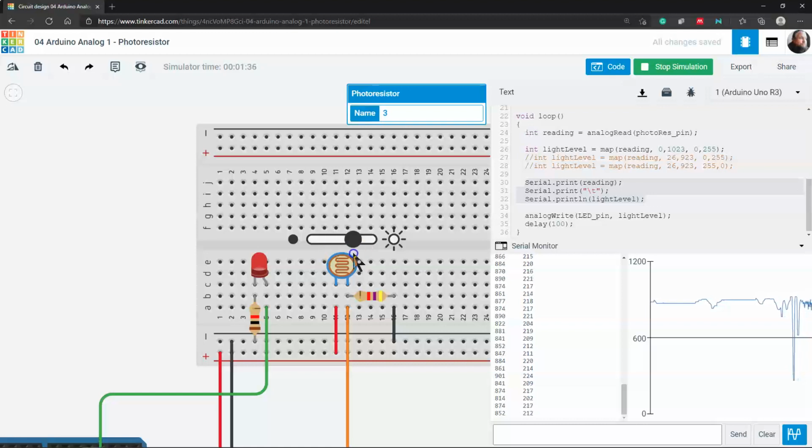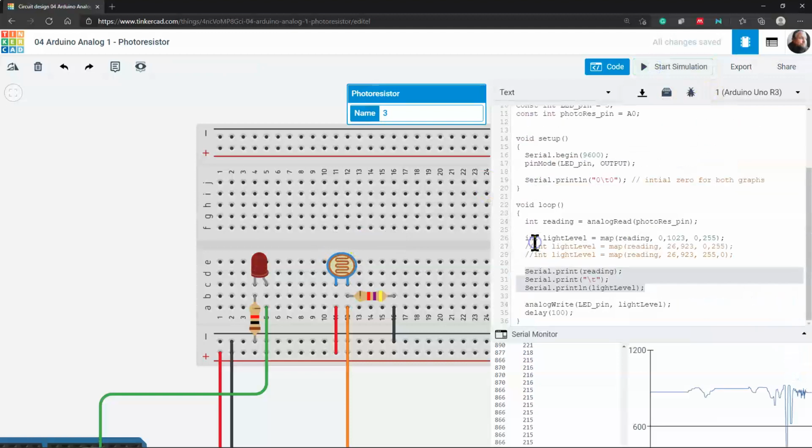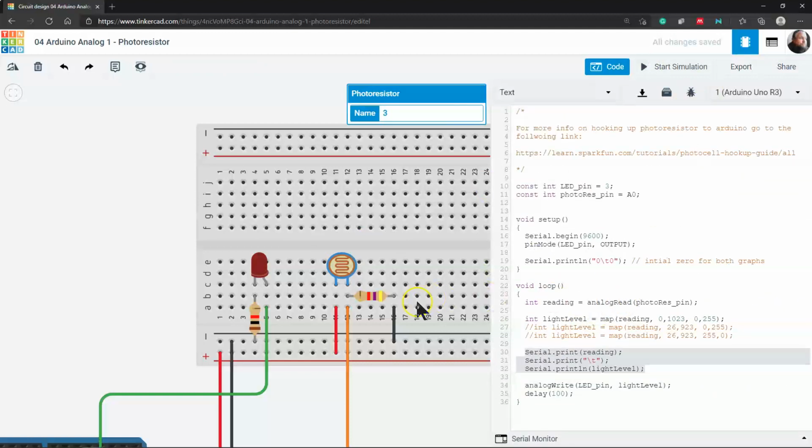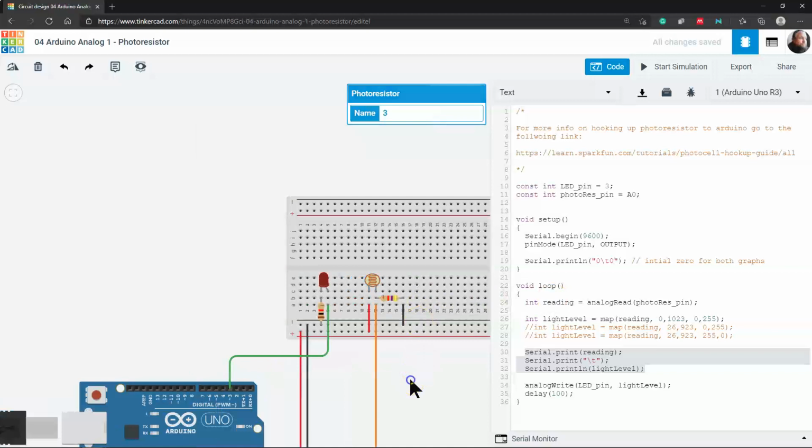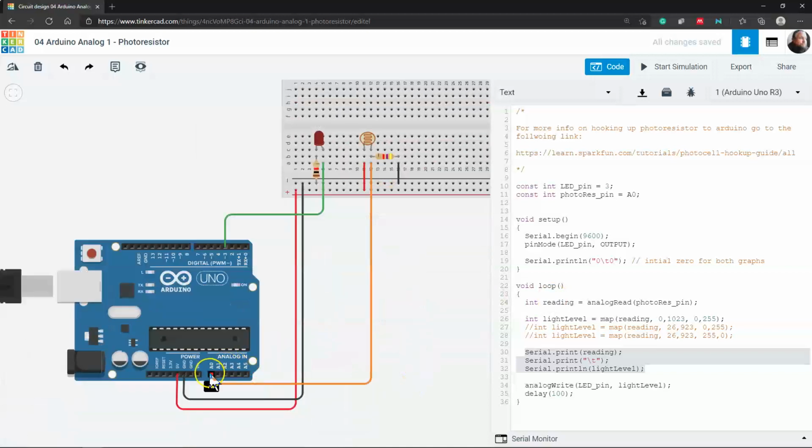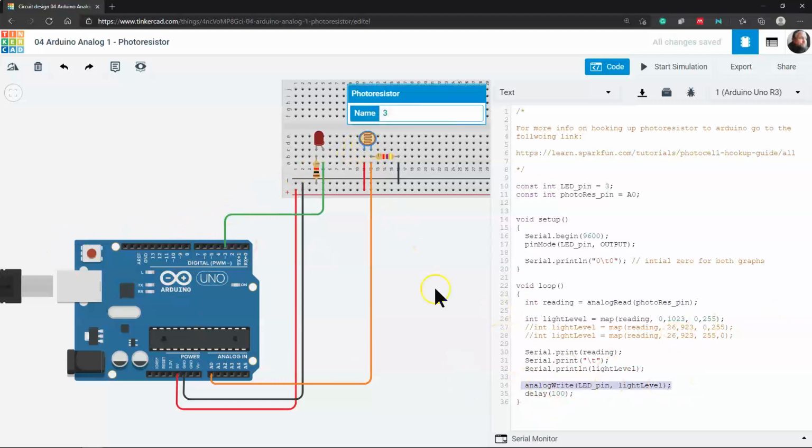And like these jitteriness, and as it keeps going. Okay. So you have your first example there of working with any kind of analog input. The key part is it's really just about hooking it up to these analog input pins, using the analog read, and then if we want to do anything with PWM to simulate it, having an analog write over here. So just because this is a photoresistor, if we change it to another analog input, it's still going to be connecting up to here, and you still have these same reads.